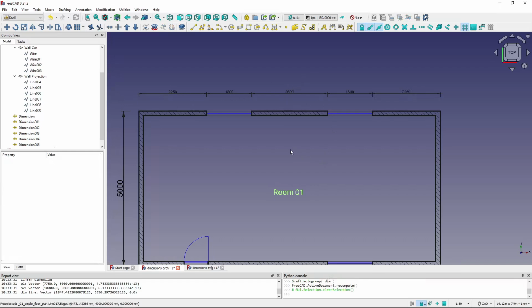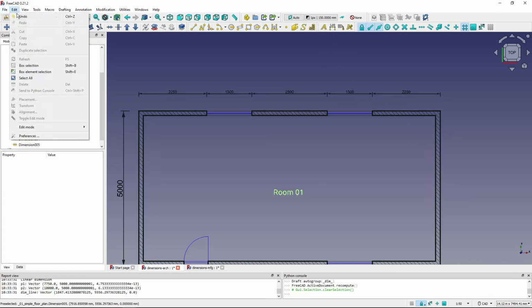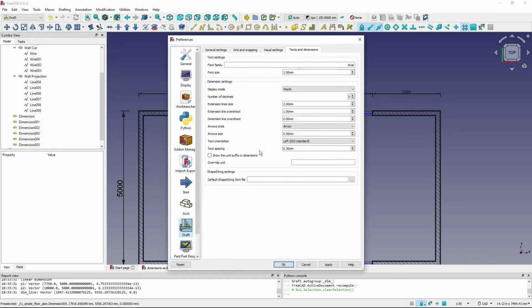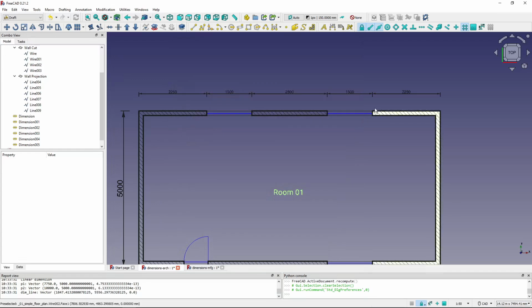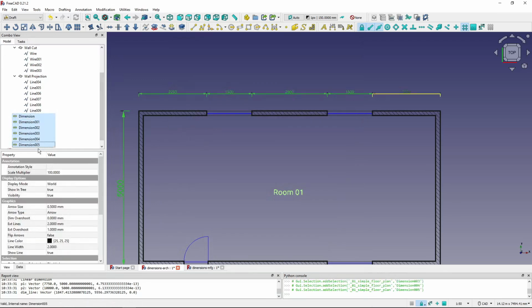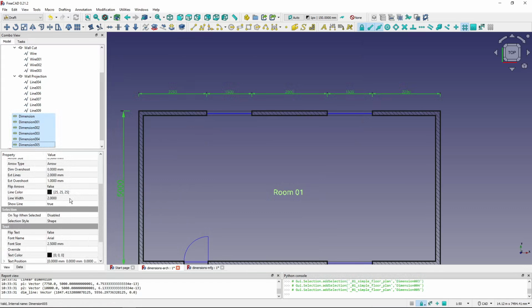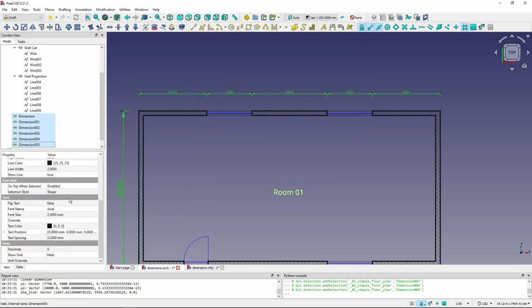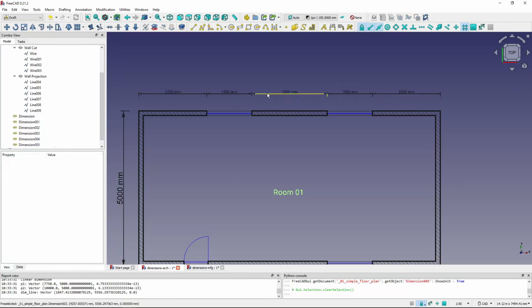One confusing thing that I would like to mention is if I'm using the standard or meter kilograms seconds degrees, when I'm using the dimensions, and I will change the preferences to show suffix, and I will select all of these, and I will text show unit. I will change it to true. Now I've got these millimeters.